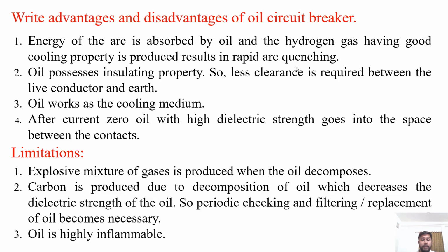The absorption capacity is very high and the arc quenching is fast. Oil possesses insulating property, so less clearance is required between the live conductor and earth. Oil works as the cooling medium, and after current zero, oil with high dielectric strength goes into the space between the contacts and quenches the arc easily and effectively, and in less time as compared to air circuit breaker.